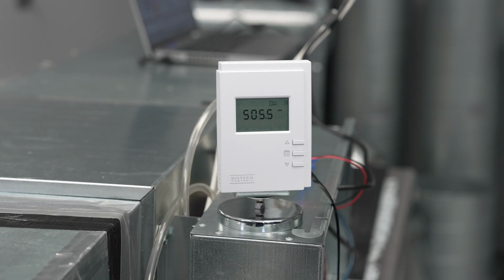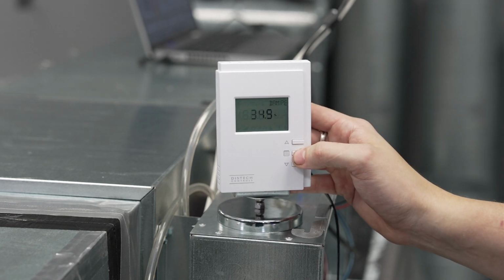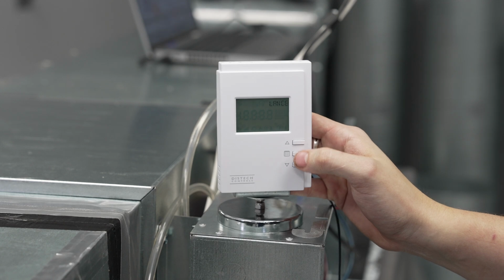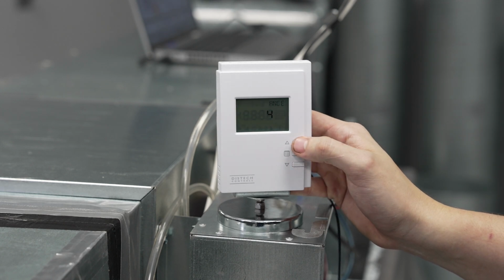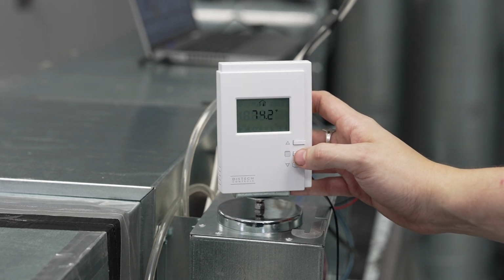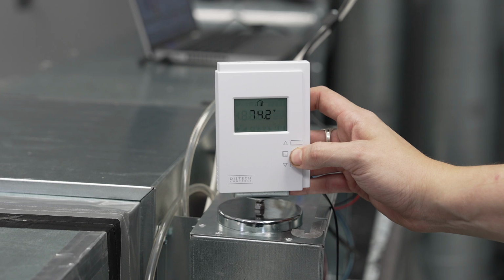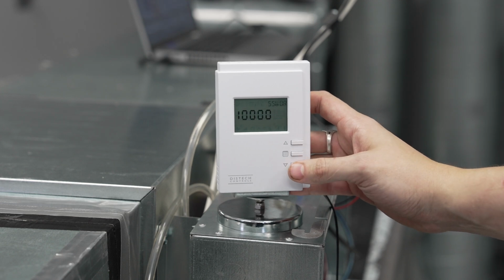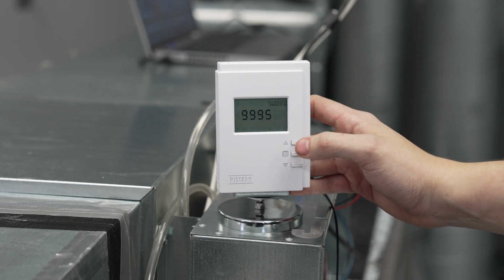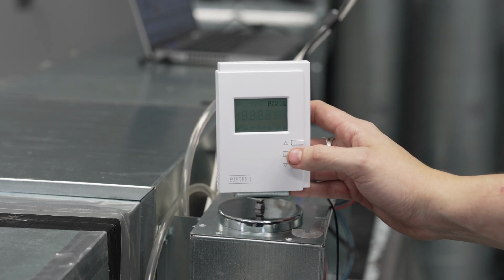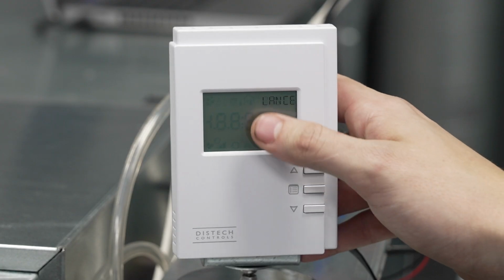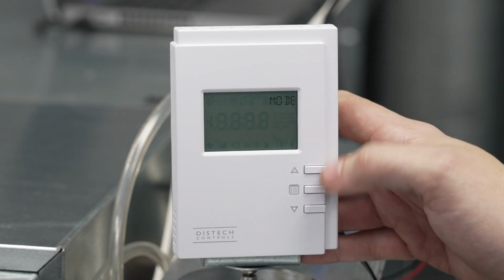Whether using the thermostat or control software to navigate the various control states of the SACV, when using the thermostat, this will be performed by holding the central button for a few seconds until you are prompted for a password. For this unit, the password is 9995, after which you will enter a configuration menu. You will navigate to the balancer mode, press up to enter, and the mode to look for is mode 4.